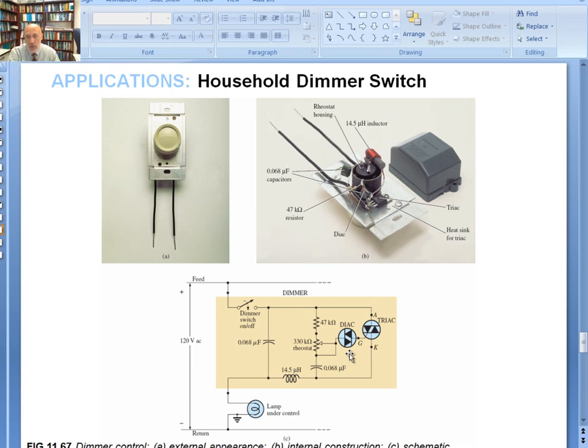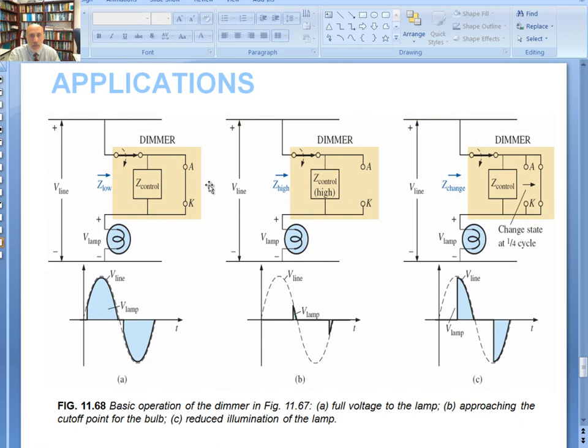If you look at a sine wave, half of the cycle is positive, the next half of the cycle is negative. So you have to have a bidirectional device to control the signal. So when the voltage is high enough, it will turn on the diac. The diac will develop a voltage right here at the gate of the triac. When that triac is turned on, then it will establish a very low impedance, so it acts like a short circuit, and that would be the case right here.